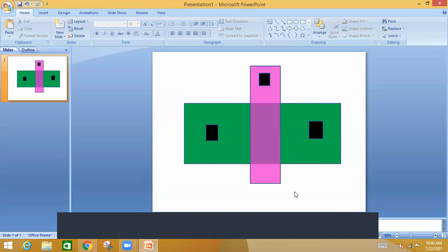Sometimes what happens, this is not sufficient. So that's why you need to increase this much area here only. Then you need to specify this is 2 lambda by 2 lambda. This much is minimum lambda. So this becomes 4 lambda. This has to be 3 lambda, this has to be 2 lambda, 2 lambda. Again this is 3 lambda, and 1 lambda like that. Okay, then what is remaining?